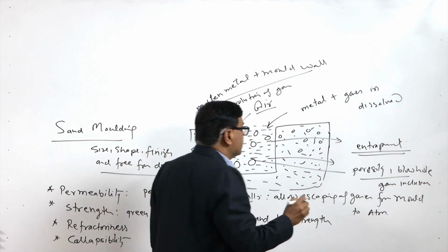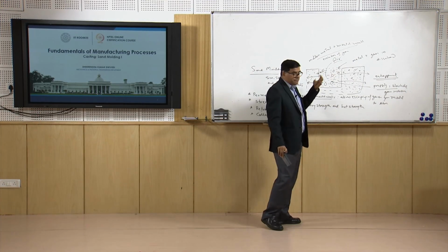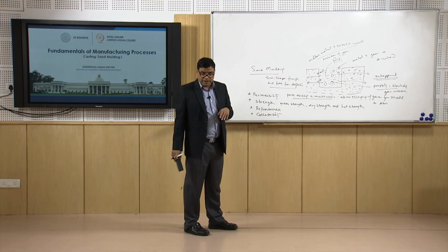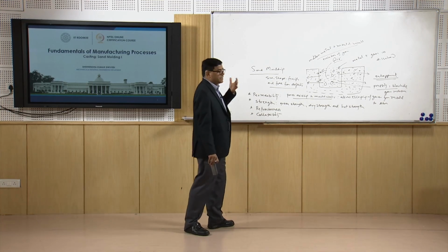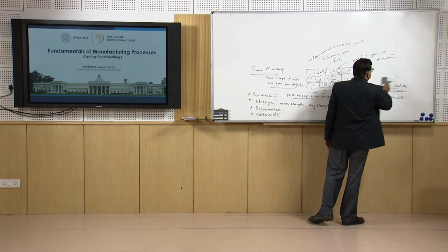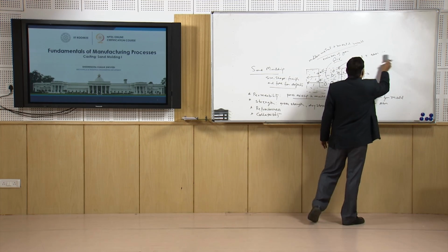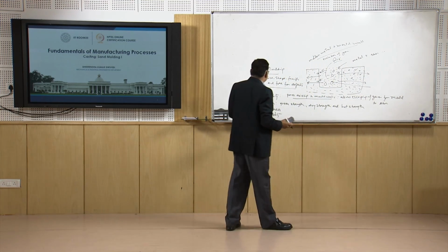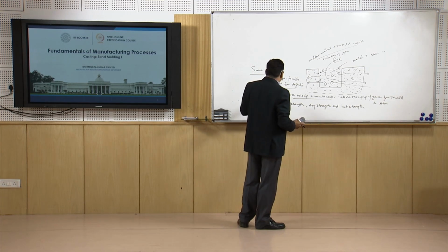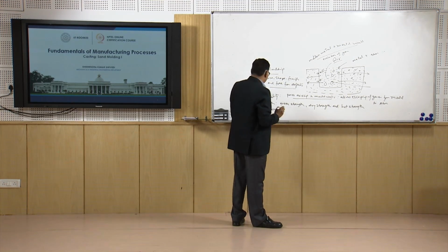These are defects, and the presence of these defects makes the casting of lower capability in terms of the ability to take up load, or increases sensitivity to corrosion, or the tendency of failure during service. So, in order to avoid such undesirable features related to the presence of gases in the casting, it is necessary that the permeability of the mold is quite good.